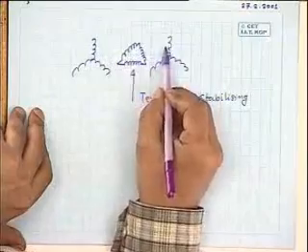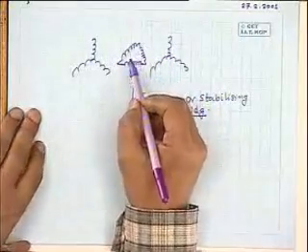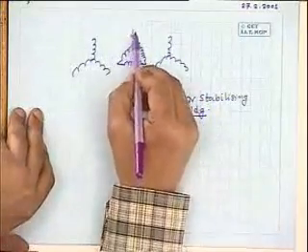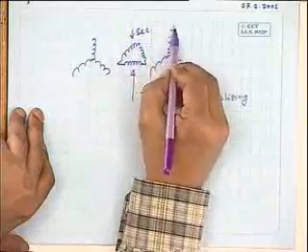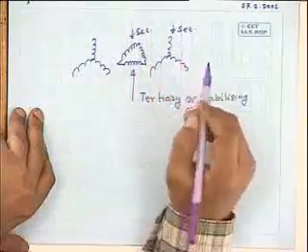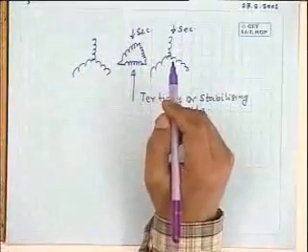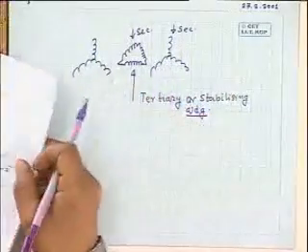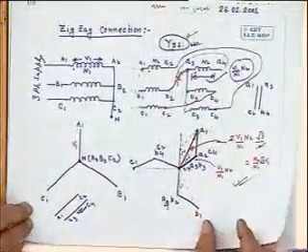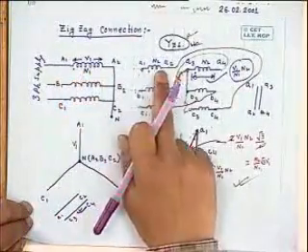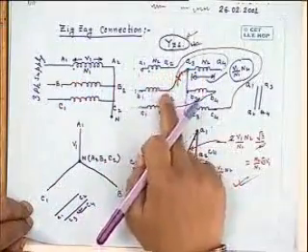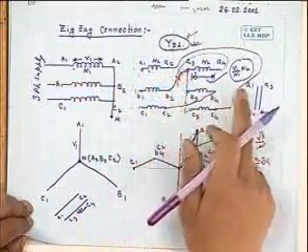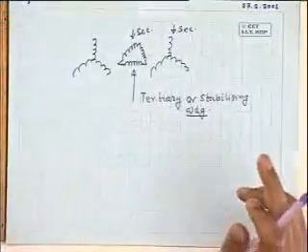That is, for each primary there will be two secondaries. One set of secondaries will be connected in delta. This is, secondary. This is secondary. This is also secondary. Like our three-phase transformer connection. Suppose you have a transformer like this. Primary one winding, two windings. So one set you connect in delta. Other you connect in star.